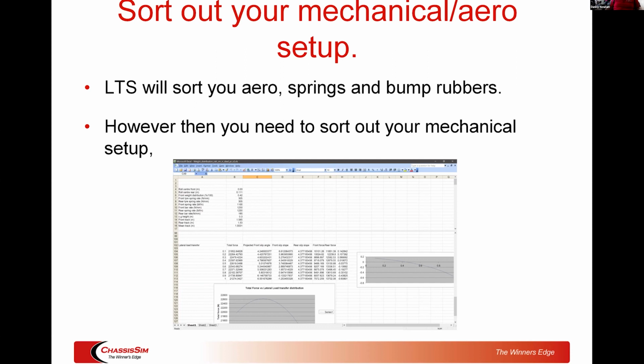That stuff pops out really quickly. Once you know that, you can then use a little Excel sheet combining a very simple tire model to allow you to tune in the lateral load transfer distributions that you're after, and in particular, that balance between handling and that balance between grip. It's a very, very powerful tool. And again, it's in that link, ChassisSim tire modeling from nothing.